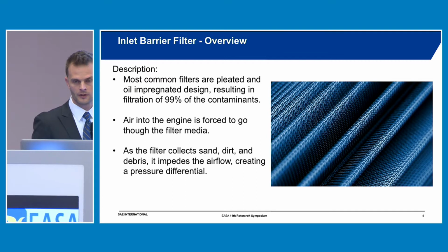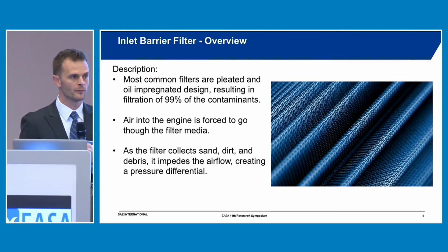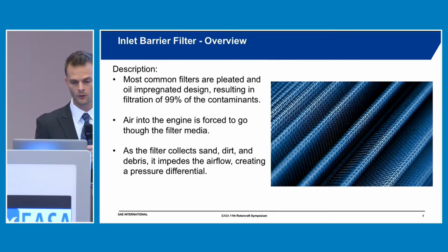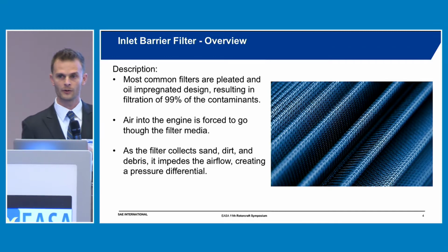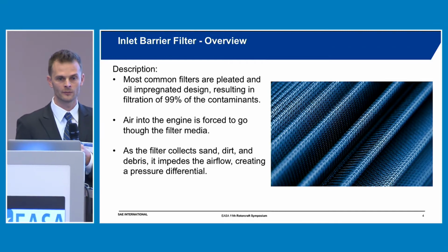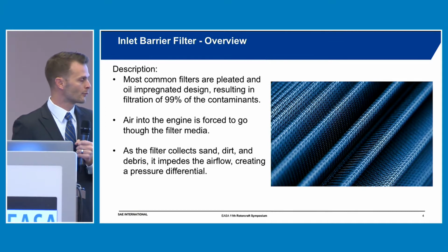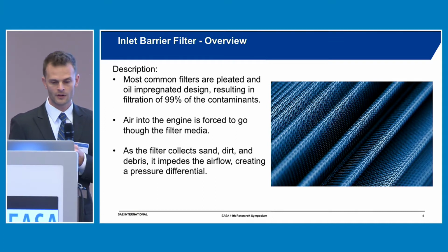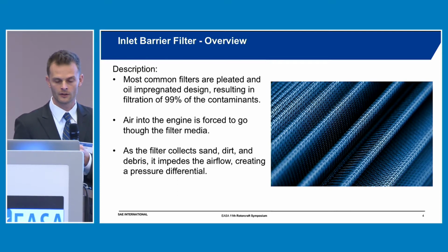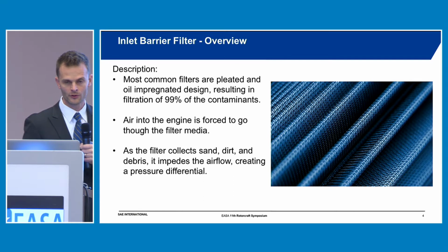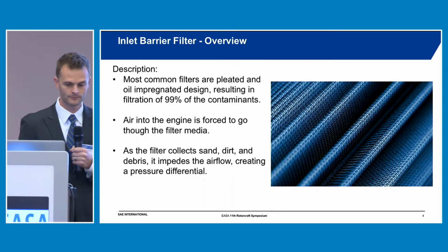In general, the barrier filters are made up of a pleated and oil-impregnated design. Typically, we'll see 99% or better filtration efficiency. There are some products out that are using a dry media that doesn't require oil. Basic concept, the air that used to go in the engine is forced through the media.